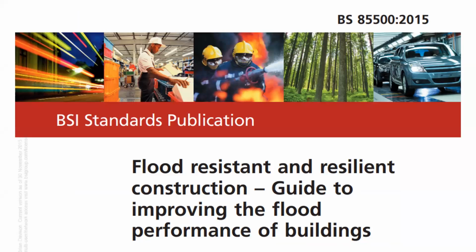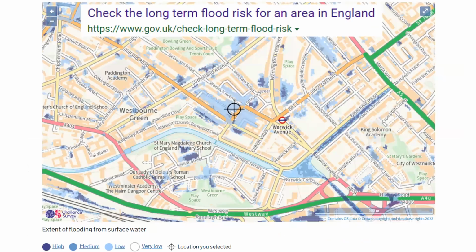And that's the standard for flood resilience. So that's referenced in the BS 8102:2022, and it wasn't referenced in the previous standard. So that's important, part of our risk assessment. If we want to check if a basement site is going to be in a flood affected area, we can go on to DEFRA websites and various government websites, and we can look at maps. We can see, does the site have a history of flooding? Is there a flood risk? And we can factor that into the design, can't we? As part of our due diligence, looking at the site conditions.